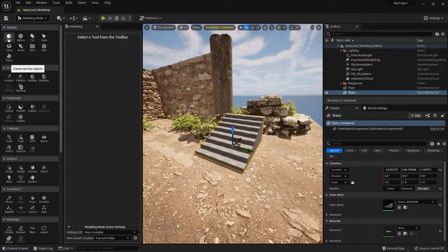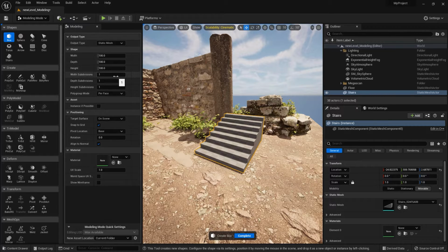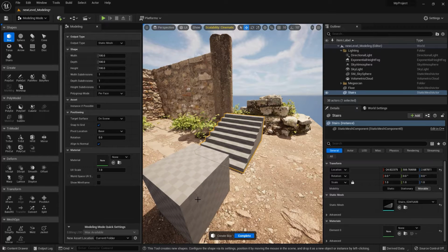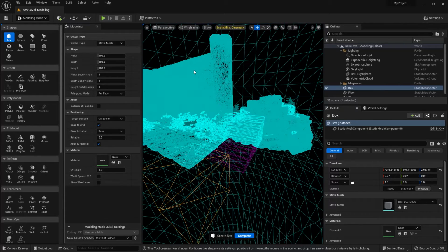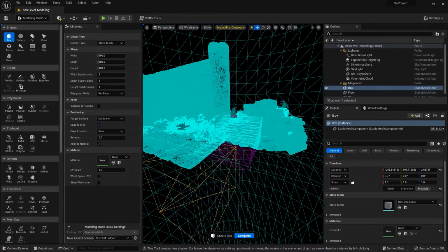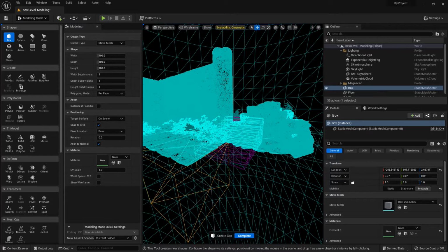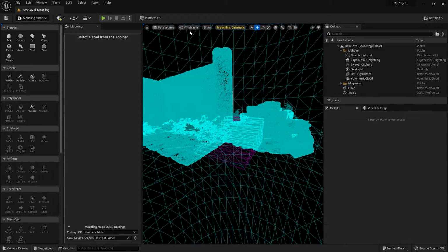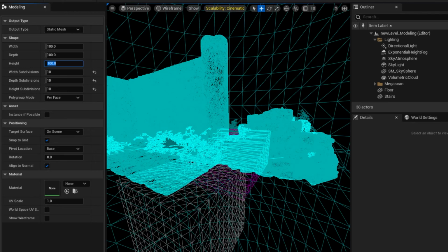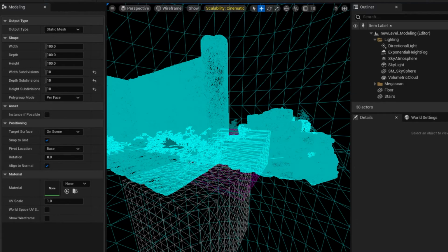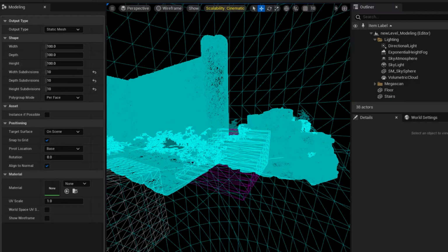Now, a lot of these attributes are actually similar in the shapes rollout. You click on that and you can see, for example, for a box, we have subdivision, which is set to 1 and 1 and 1. If I go and switch to wireframe, you can see that cube or box is super low poly. You can change that if you want to get a much denser model. You can go in here and set that to 10 and 10 and 10, and all of a sudden you see that what I'm getting, the wireframe, it's actually super detailed. So that's another way of doing this.